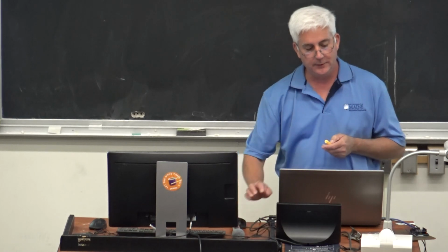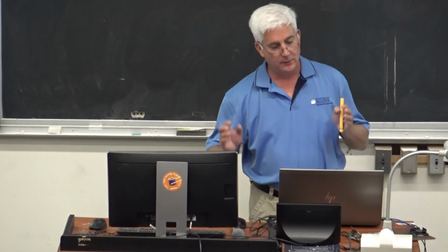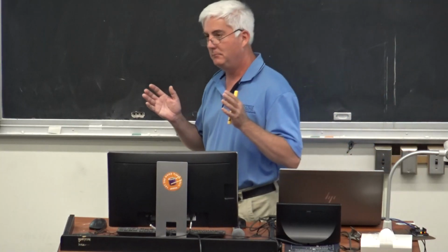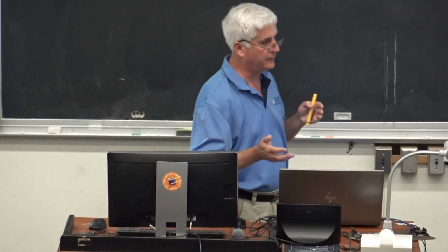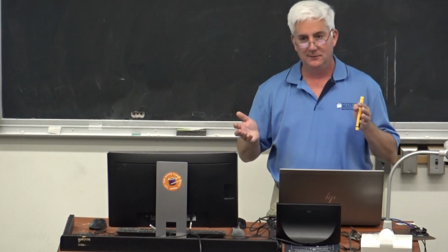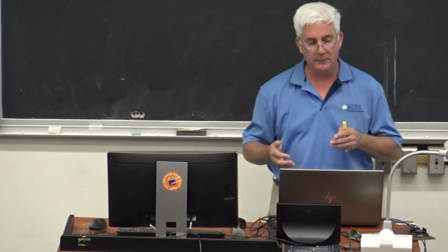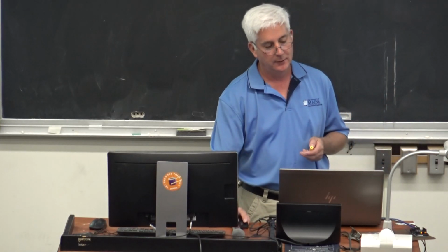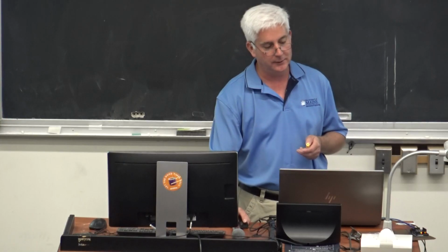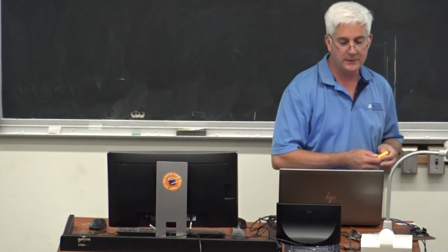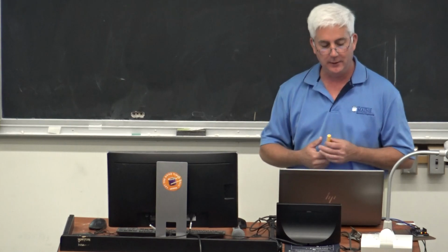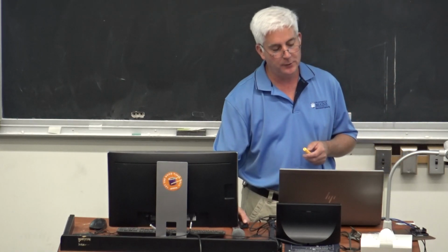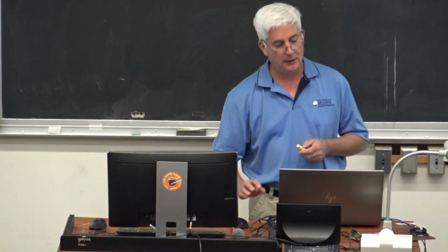Next thing I'm going to do, so I've got this bits value coming out of A0 in the range of 0 to 1023. Okay, so not really useful. So the first thing I'm going to do is convert it to voltage. I've got a variable called A0 voltage equal to my average sensor value times 5 divided by 1023. Simple scaling stuff. And then I output that voltage and then output a comma.